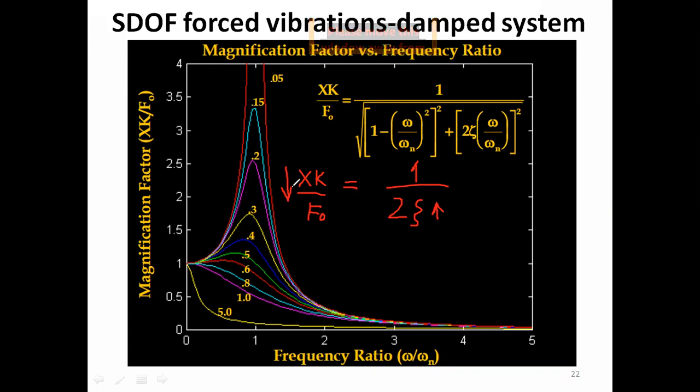So that is a very important conclusion from the model or simulation. If we take no damping in the system, if I put zeta as 0, then the model says it would be 1 over 0, and 1 over 0 is infinity. So in case of an undamped system, the magnification would become infinity.